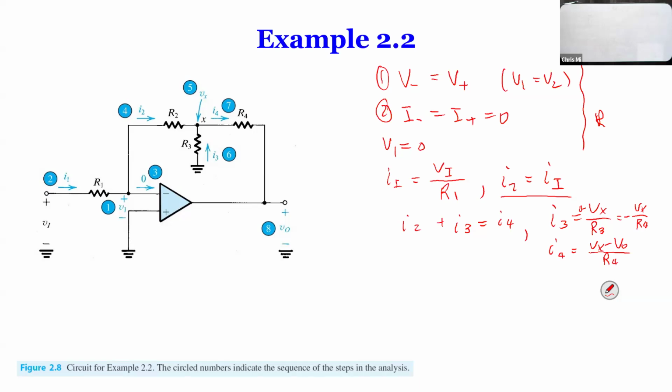So, well, the point is that we now introduced Vx. We want to find Vo, but we introduced Vx. So we have trouble. But fortunately, we know Vx. Let's do this. 0 minus Vx divided by R2 equal to how much? Say 0 is here. The inverting terminal is 0.